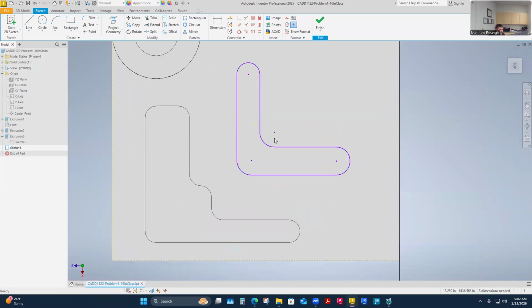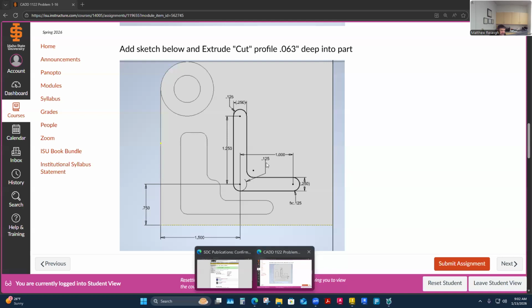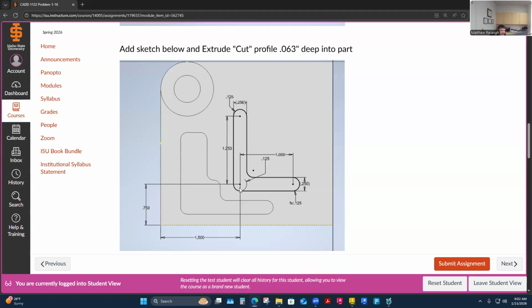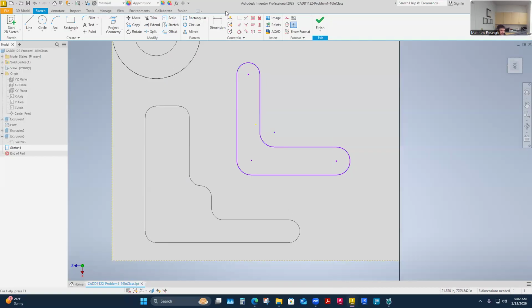I've got the fillets the same size, I think, all the way around this thing. I think they're just 1/8 inch. Yes, 1/8 inch fillet. So this one here is one way I told you could do it. I can tell how the sketch has two different 1/8 inch fillets, even though they're doing the same thing, and then this one's being driven by one of those. So I don't love the way this one's been constrained in some ways. I'll probably use my equal again here. So I'll dimension one, that these fillets need to be 0.125.